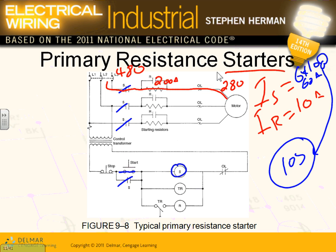280. So I started my motor at 280. I reduced the voltage momentarily. So by reducing the voltage, remember that formula that we were looking at? When I reduce the voltage, what happened to the current? It goes down. That reduces the inrush.